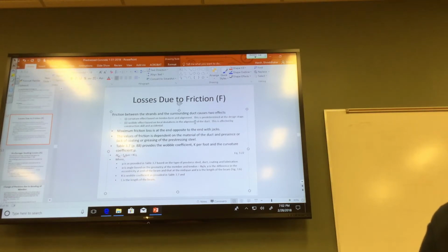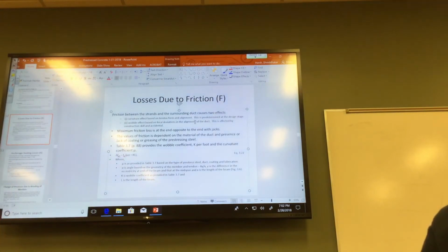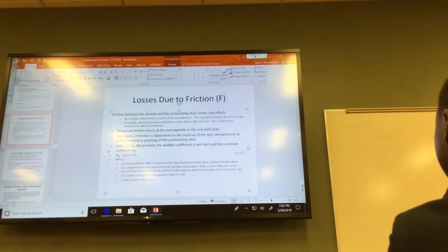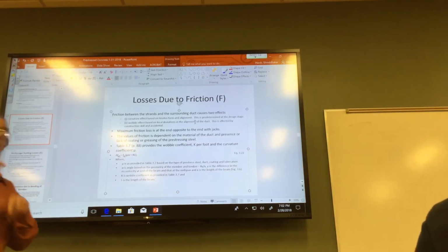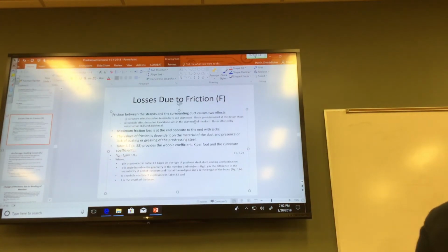So anyway, we have a friction coefficient. Friction loss is because where you have a kink or where you have a profile and you're trying to stretch it, it's going to rub on some surface somewhere, right? On the part that has the minimum and maximum points. So suppose most of the time we are dealing with a simple supported beam. So it may be a profile like this, or you may have a profile like that, right?